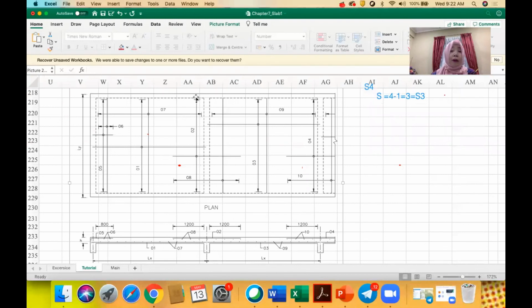Okay, you draw the plane here, and then for example 01, 01 is the near middle of end span. It must start here, yeah, one cover from the beam here. One cover here, to here, one cover from the beam, and just draw the arrow here, and then draw one steel only to represent many of the steel here.